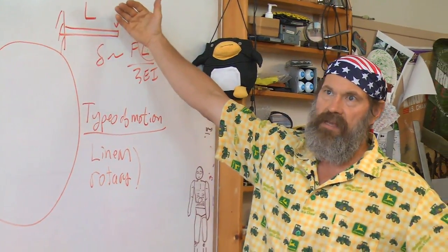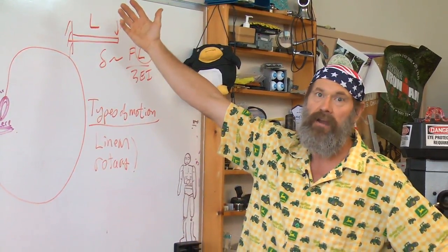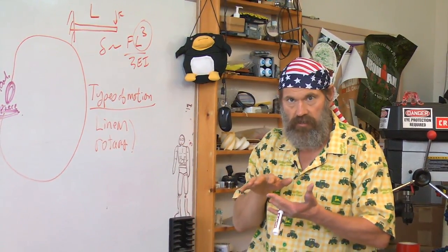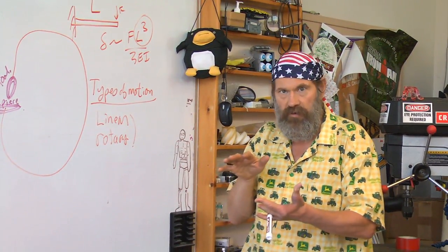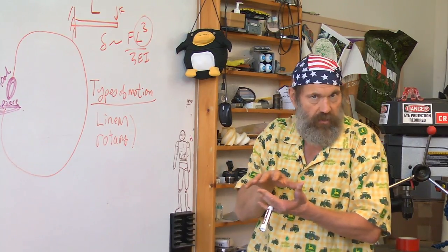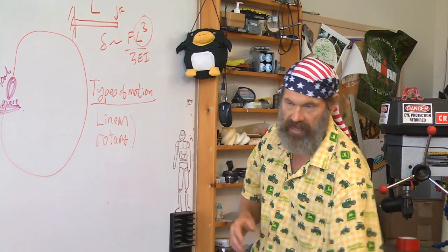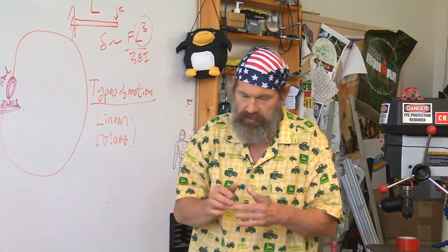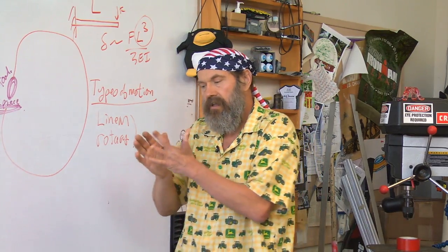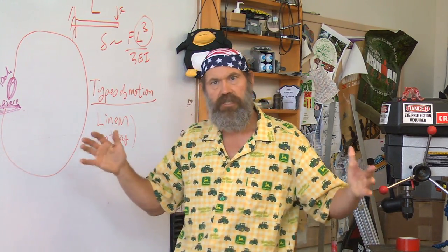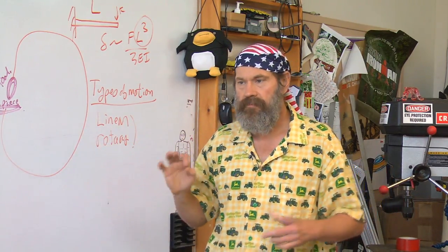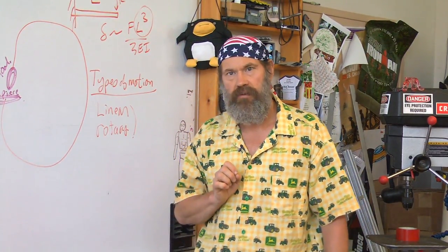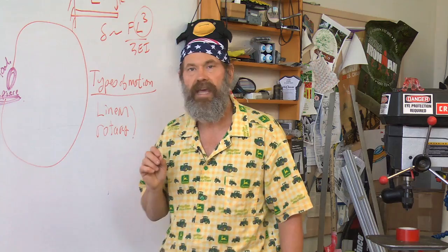So having a great big machine to accommodate any size part when you're mostly operating on little itty bitty parts may start to tell you that the cost of that machine is going to go way up in order to give you the stiffness you want for operating in the small zone, and you may be far better off having a family of machines that'll handle from small to medium parts, and then from medium to large parts, and then large parts, as opposed to one machine that you're going to use for everything. Okay, so that's another key point. This is not only true when you're designing machines, but when you're buying machines to accomplish a function, what you may expect to pay.